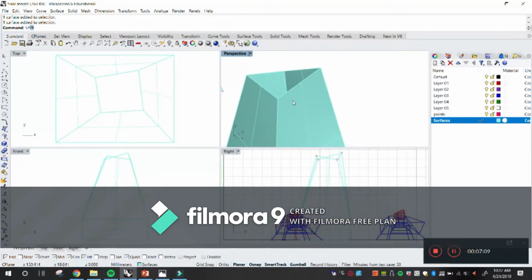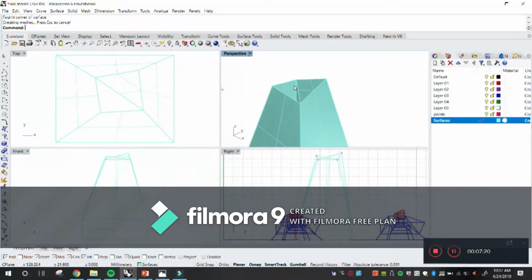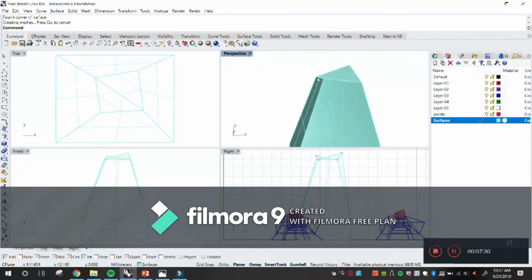So again, surface from points, right? Now I want to stress that it's surface from how many points? 3 or 4, right? That means I can do 1, 2, 3, right click, and I'm done. I don't have to do the 4 points, right? So 1, 2, 3. Whoops. But see, for example, there, I snapped. No, yeah, I snapped to the right location right there. So I have capped that.